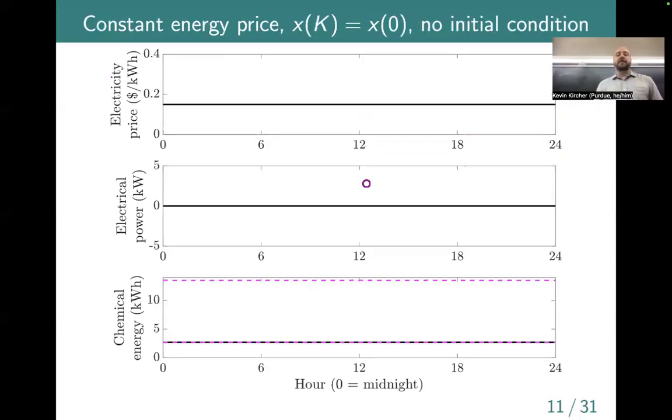All right, so that was, what if we put in a price that values the energy at the end? Here's another option: impose an equality constraint that says the final energy has to equal the initial energy. We can delete the constraint that says we have some pre-specified initial energy x naught, and leave that as a variable. You can choose wherever you want to start in the battery, full or empty, but you have to end in the same position that you started in.